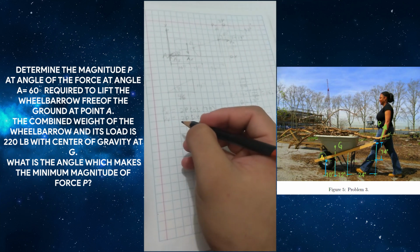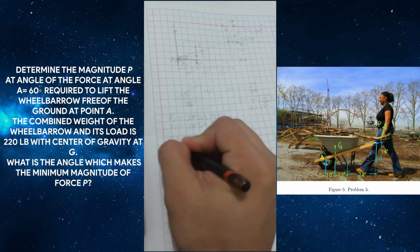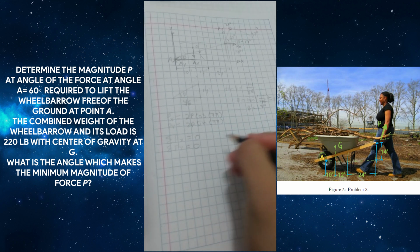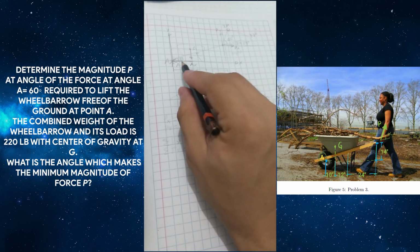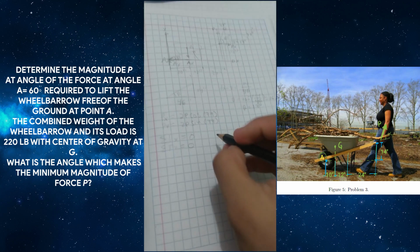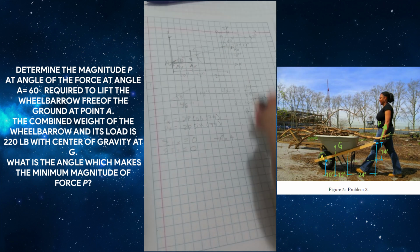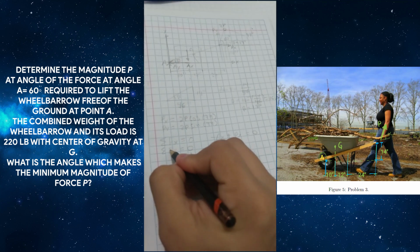So now we need to use the following conditions that says that the sum of the forces in X must be 0 and the sum of the forces in Y must be 0. So for the first condition, we need the force Ix that is in left direction. So it is minus Ix plus Px equal 0.